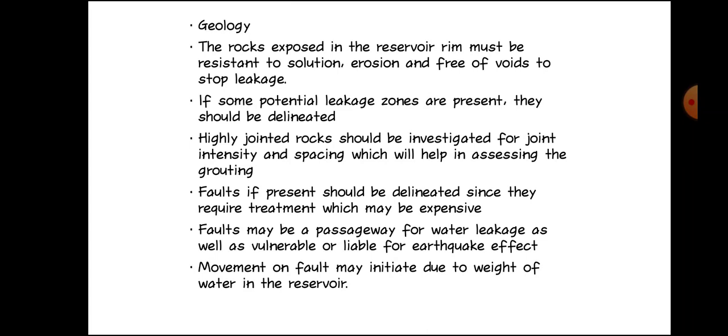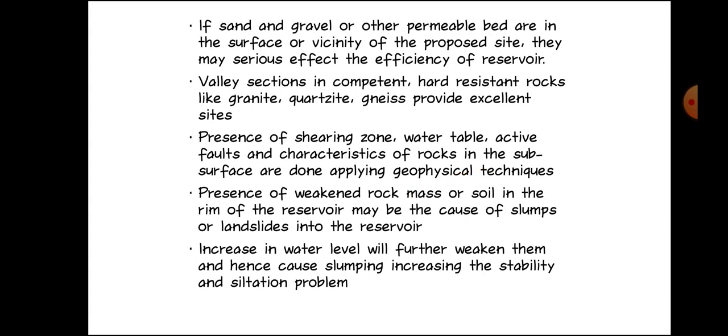Faults, if present, should be delineated since they require treatment, which may be expensive. Faults may be a passageway for water leakage as well as vulnerable to earthquake effects. Movement on a fault may be initiated by the weight of water in the reservoir.